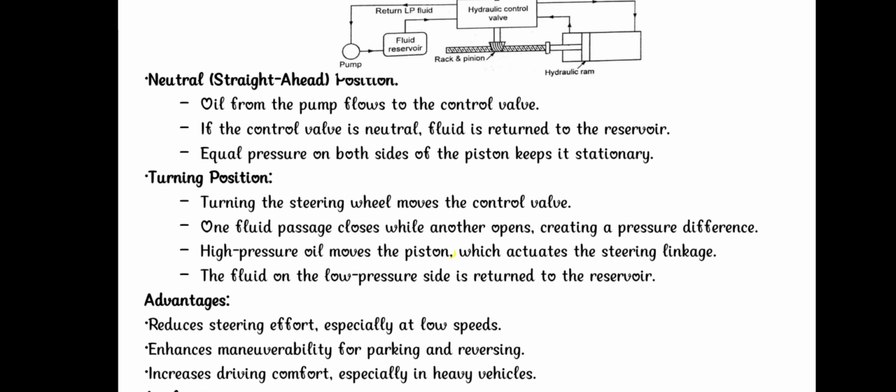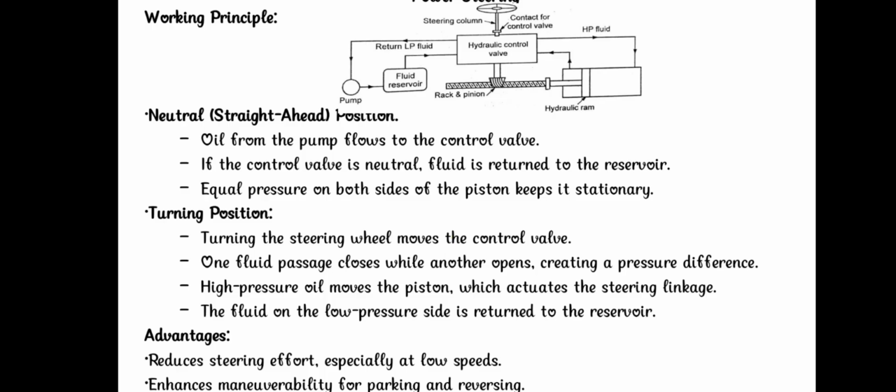In the neutral, straight ahead position, oil from the pump flows to the control valve. If the control valve is neutral, fluid is returned to the reservoir. There is equal pressure on both sides, so the piston stays stationary.